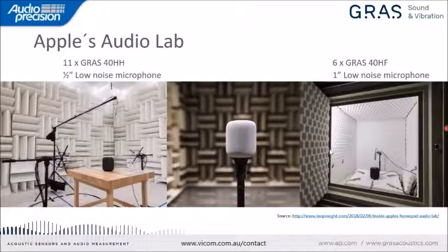You can read more about this in the source link we have over here. But I think it's important to note that particularly in the first picture, you can see hints of a setup that is based on the ISO 11201. So we have a hemi-anechoic chamber here, and we have the ISO 7779 test table.